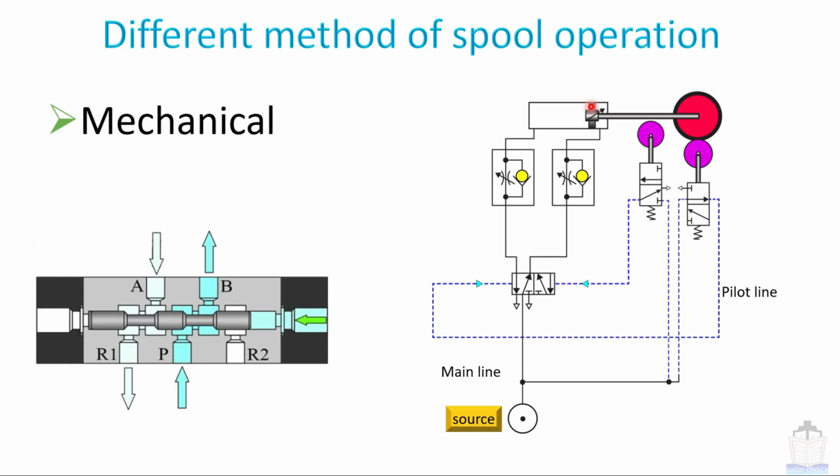As for the function, I am just going to explain this valve. You can see this is the bigger cam which basically operates these two pneumatic valves, and it is controlling the pilot air which is going to this 5/2A valve, and accordingly the spool shifts and either the air flows through this valve or through this valve, and hence the pressurized air acts either from here or from here, and this whole piston gets shifted from this place to this place, and all this functions automatically. Now I am going to show you the same thing with the help of animation so that you can understand it in a better way.